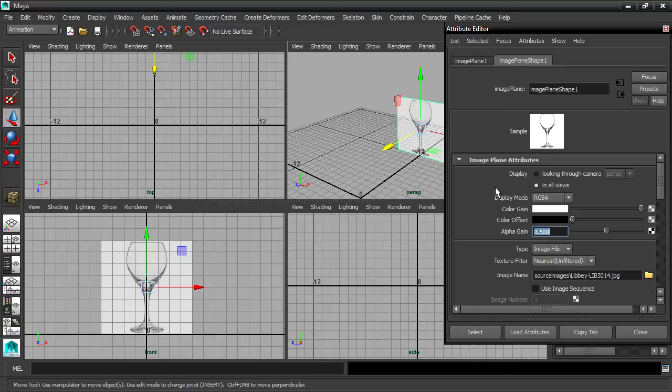Okay, now we're at a good place where we can actually save our first version of the file. I do recommend that you store multiple versions of everything, even something simple like this. I never have just one version of anything in Maya. It's so easy to run into problems in a 3D program, especially a complicated one like Maya, that you need an insurance policy. You need a time machine. You need to go back to yesterday or 10 minutes ago, before you did some destructive command that messed up your scene. So to avoid future problems, always version your files.